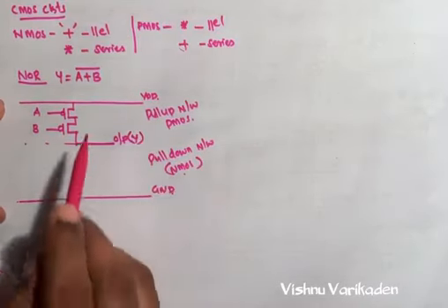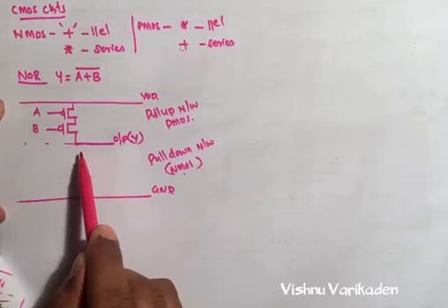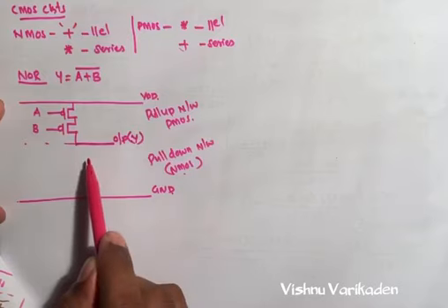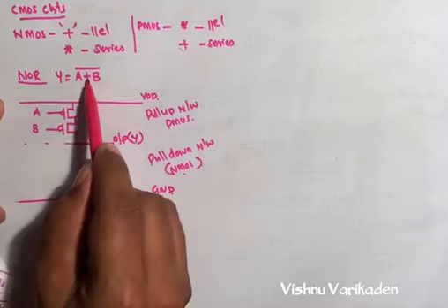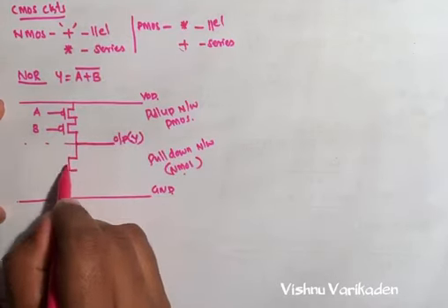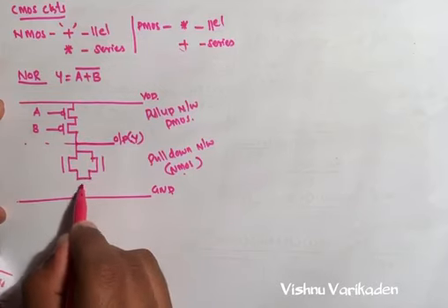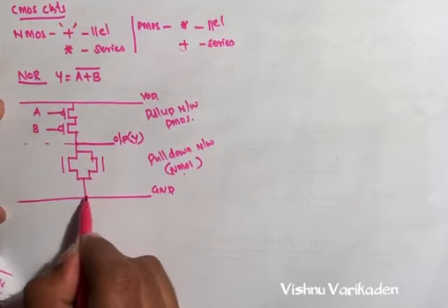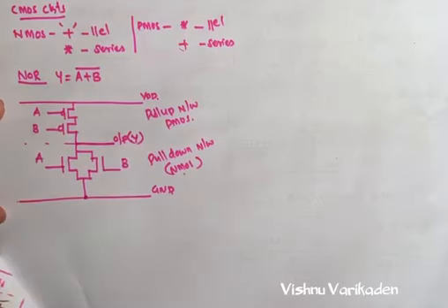So we can make the plus operator here. So this is the area for NMOS. This area does not contain PMOS, only NMOS transistors. So the plus is here, so the plus is parallel, so the NMOS is parallel. So this is the parallel connection to ground. This is A and this is B. So this is the CMOS circuit.